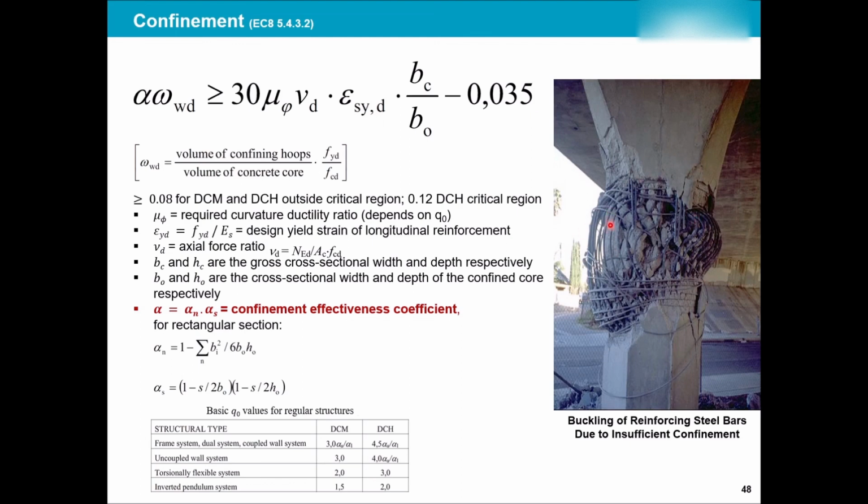Earthquake strikes, and the spacing and the confinement resistance of these hoops weren't sufficient. As you can see, bending and buckling of all the steel reinforcement, and the complete failure of the bridge pillars, which is a disaster for whoever has designed it. You can literally see the core concrete getting out of it as well. These hoops shouldn't have existed like this, so they're all broken and taken outside. You can see it landing here.